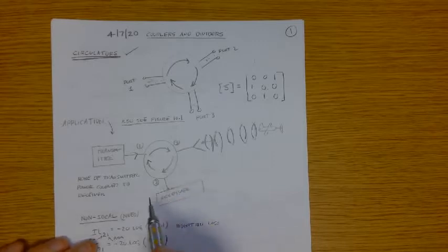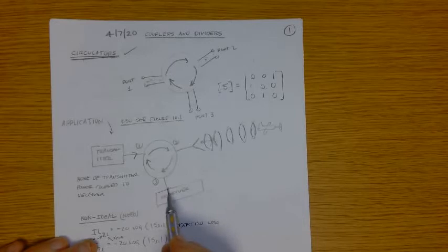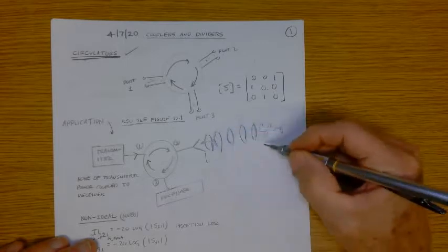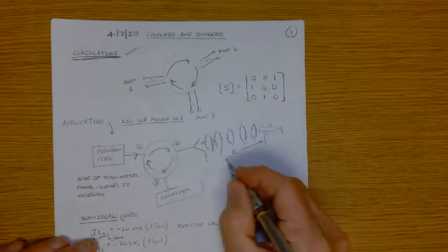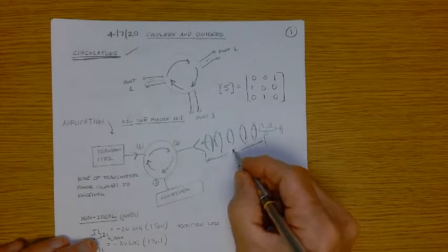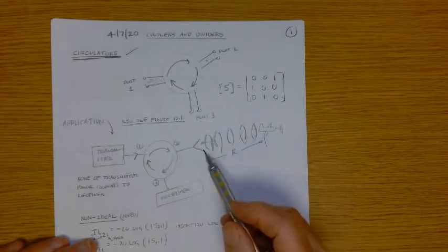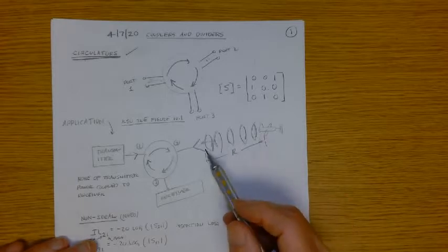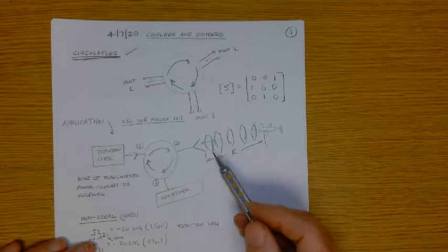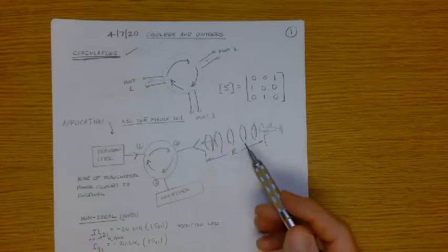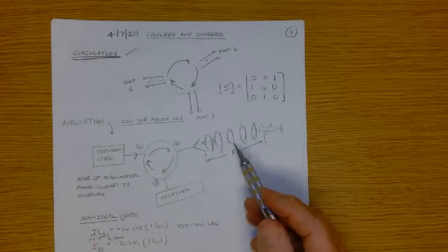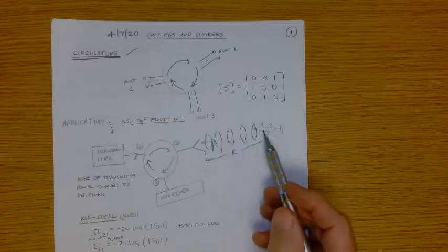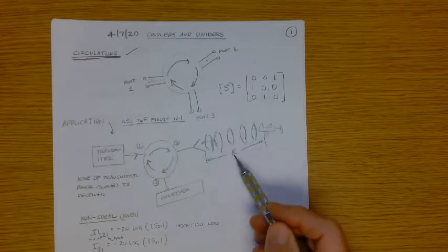Also, the receiver is very sensitive, because it has to pick up very weak signals reflected from the target over typically large distances r. So we know from the Friis transmission equation that going forward, power goes like 1 over r squared. The back goes like 1 over r squared. So in the radar range equation, which we never developed, but I think Stu develops in the chapter on antennas, you could read it there, it goes like 1 over r to the fourth. So that's a weak signal back from the target for large ranges.